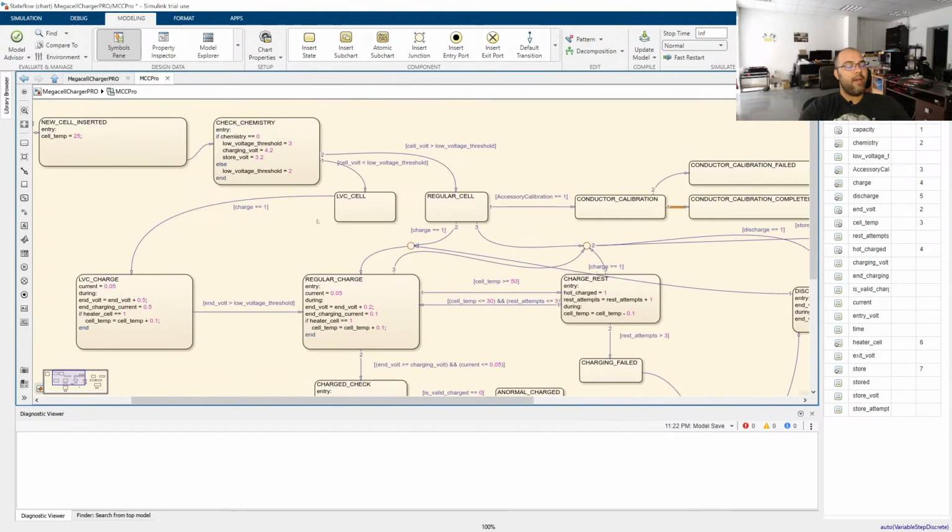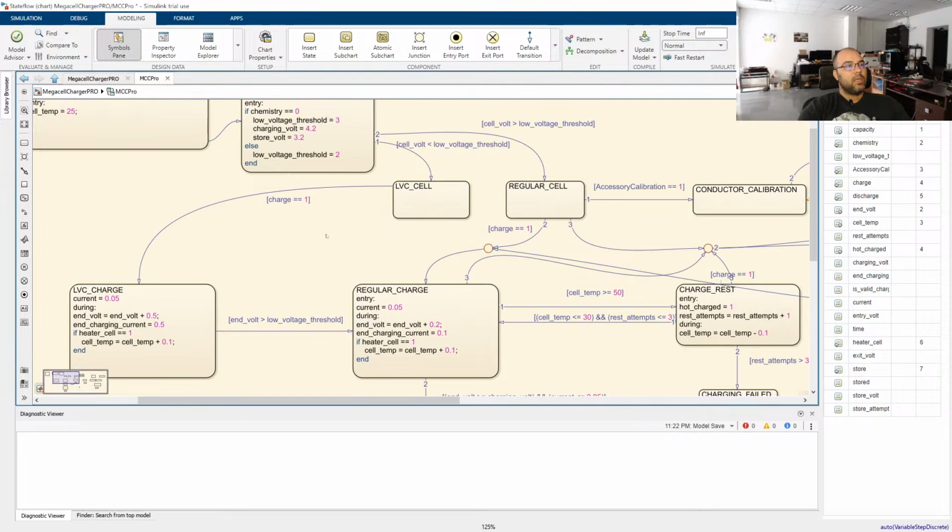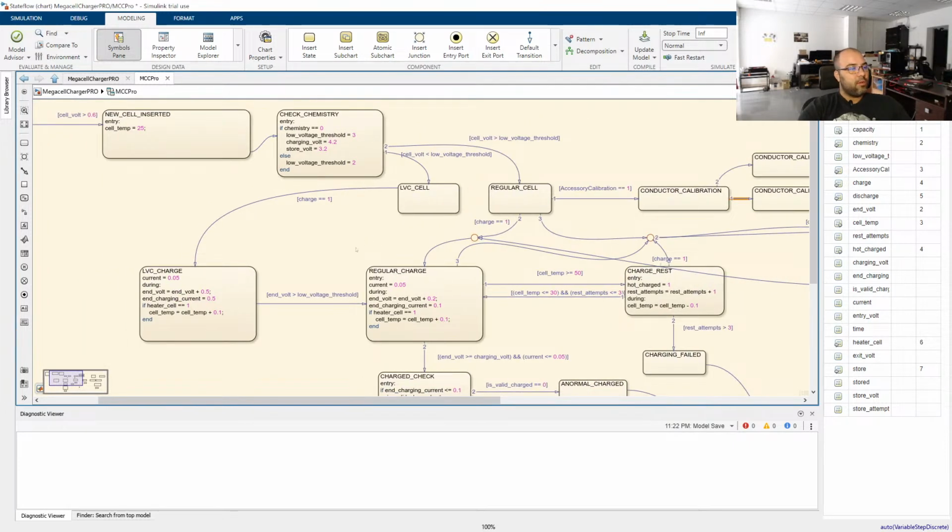And we'll have the default chemistries, which will be lithium ion, lithium phosphate, and LTO, lithium titanate oxide, or something like this. I will probably add the high voltage lithium or something like this. It's like 4.4 volts. The chip can do that, the IC for charging.